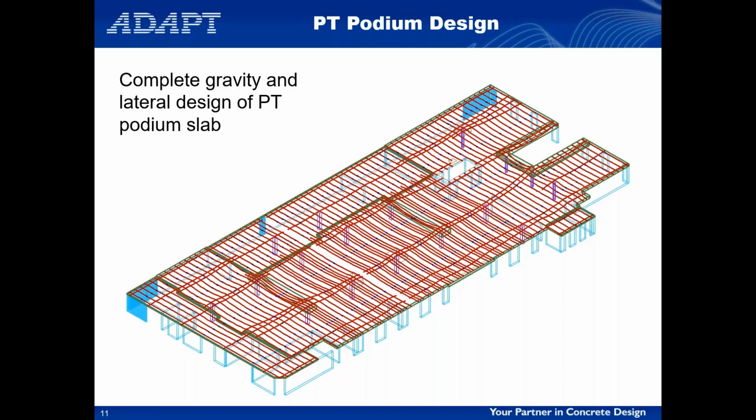So one thing you may want to consider and review in your design approach in your office is, because these podiums tend to be closer to the ground and very close to the, obviously connected to the foundation, you may choose to actually switch the default boundary condition for when you're doing the PT podium design in Floor Pro, switch that to fixed as opposed to the rigid roller.